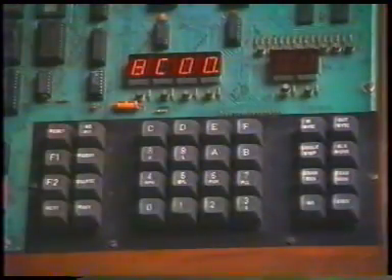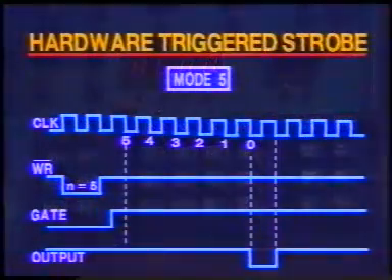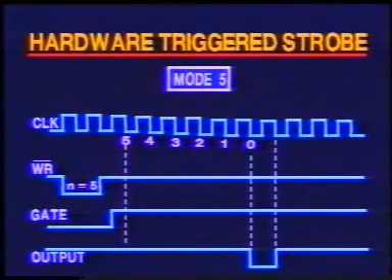The mode word and count value are loaded. The counting is started by the gate signal, that is, by hardware. A low-level pulse of 1 clock duration is generated when the count reaches the count value. The counter is re-triggerable.